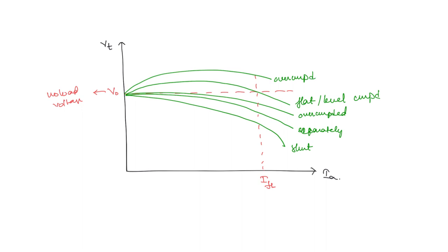What is left out now? Series and differential. So differential, anyways we know it will just fall very rapidly. Okay, so this is differential. And what about series? Series is also very different from the other ones because it is going to start from 0. Okay, so it will go something like this. Okay, so this is the series generator characteristic. So this is the comparison of various generators which is important. You have to remember.